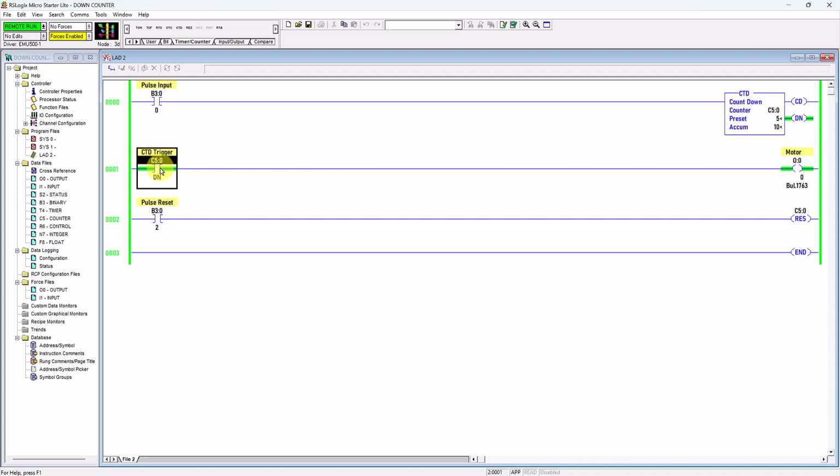If this virtual switch were originally normally closed, then it would be triggered from normally closed to open. Since this is normally open, it will be triggered to close. So the virtual power will flow through this rung to energize the virtual output coil. Thus, it will activate the external load, in this case the motor, meaning it will turn on the motor.